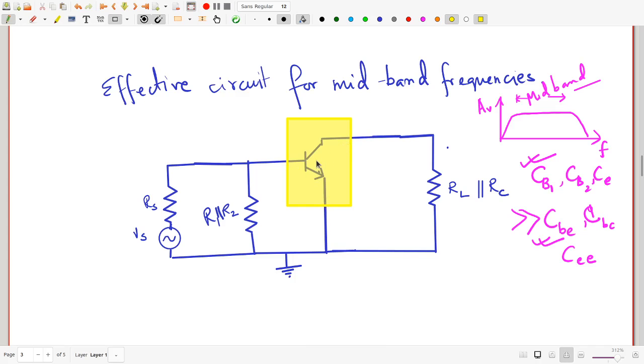And as we have learned in an earlier video, which you should definitely review now if you have forgotten all about it, we can replace two-port networks, especially when we are talking about variations or small variations about a quiescent point value, by various equivalent circuits. We could use the Z parameter, the Y parameter, or the H parameter equivalent circuit.